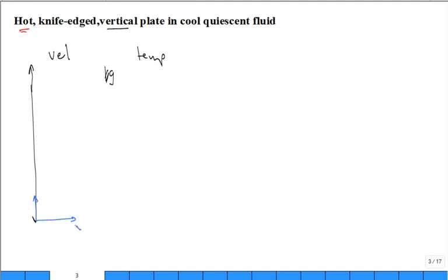And we introduce y going out and x going up. This is very common. You'd think that's kind of backwards. Shouldn't y go up and x out? Sure, but we're going to do y going perpendicular out from the hot surface. And what do we get growing right here? We get growing a velocity profile like this. So at some distance up, you can talk about the thickness of that boundary layer. The boundary layer caused by the fluid sweeping up over that hot plate.